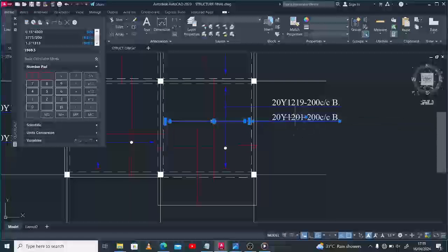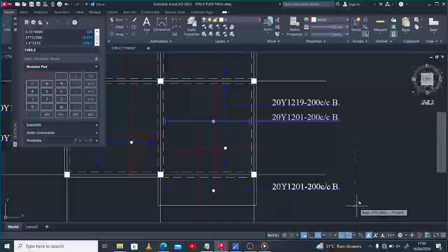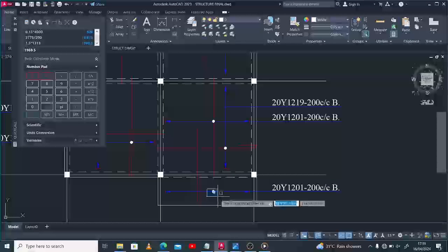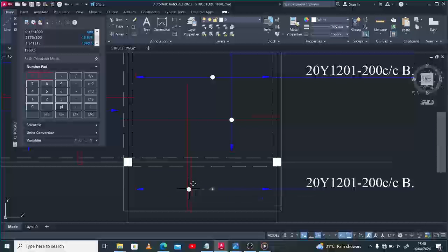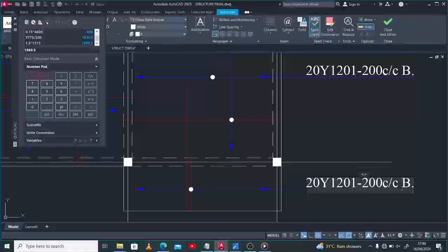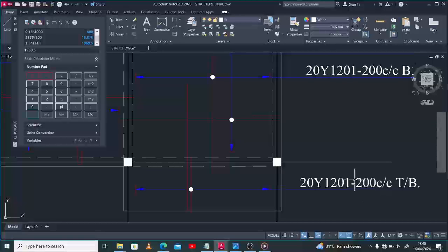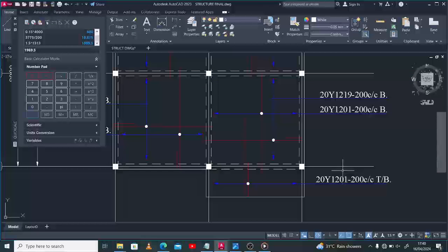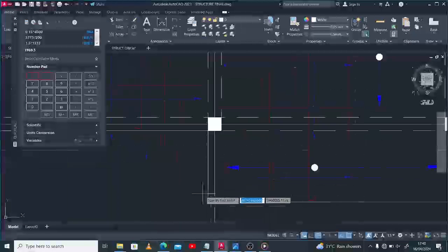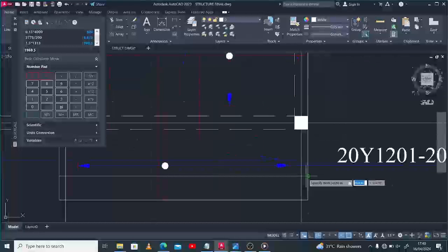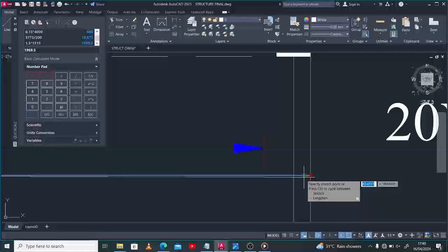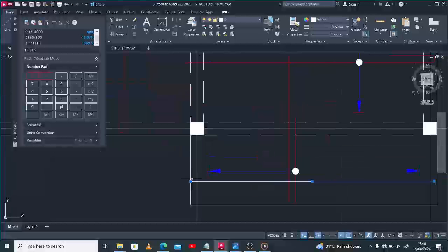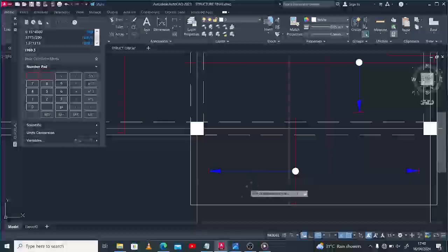So with this, let's just call out that particular reinforcement. Now this will be, because it works as top and bottom in its functionality. It works as top and bottom. Now to have the distribution of the bottom of the cantilever, we just have to create a reinforcement that goes horizontal. Then mind you, you have to keep the cover, because it's necessary for all that you do in the detailing. Cover of 20 mm for your slab. Then we do this. Great.